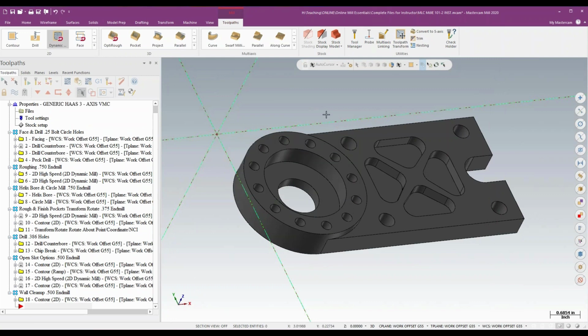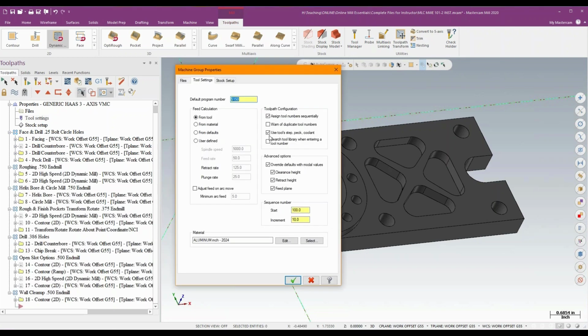We're not going to keep that toolpath. That was just to show you the auto population. But I do have to remember that is the function that allows me to do that. If that isn't checked, then it's not going to auto-populate those values. That works for milling and drilling equally as well. The drilling ops give you step or peck values if you're peck cycling, that sort of thing.